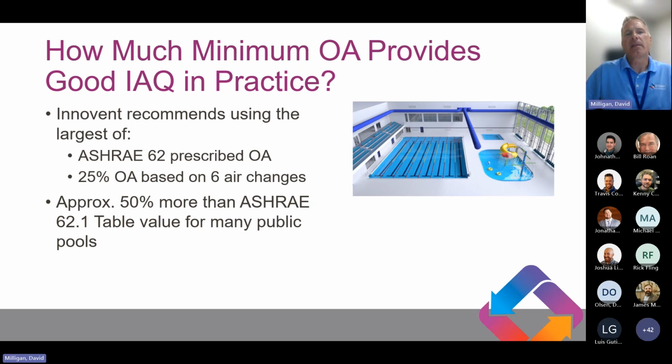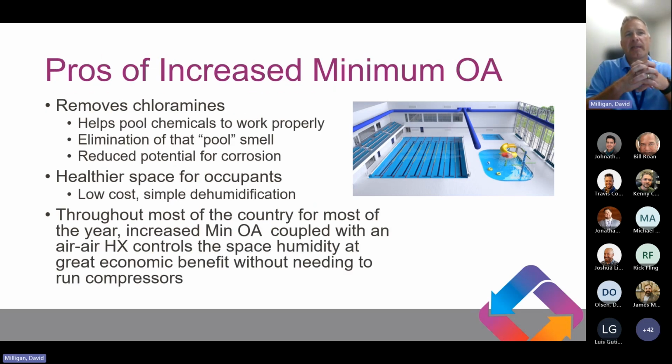And what does that mean? You know, there's a lot of nice pros. It gives a lot more ventilation into the pool space. It helps remove those chloramines. It gives us a much better, healthier space, gives a much lower cost of operation because I'm not running compressors, especially in these environments that have really dry outdoor air. Say in Denver, I'm not running compressors to do any dehumidification. I'm using that outdoor air and really bringing in a lot of nice fresh air to help ventilate that pool space.